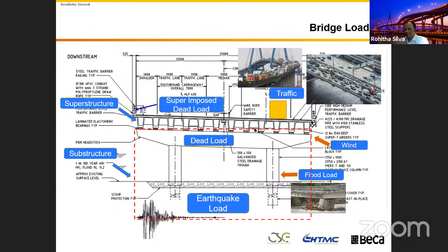You can't name the place where you're going to build bridges. Therefore, it is going to be subject to significant environmental load, what we call wind load, flood load, and earthquake load. So when you are a bridge engineer, you need to have a really good understanding of each and every one of these loads. For example, the environmental loads, earthquake, flood, and wind, you can't see them. You have to estimate them, and how you're going to apply them, and how you're going to make sure that what you are building is going to perform for at least a 100-year design life.